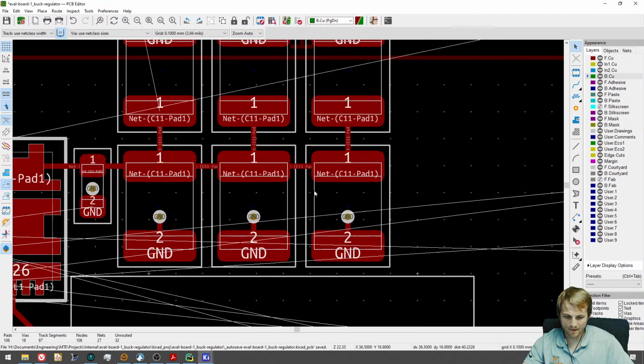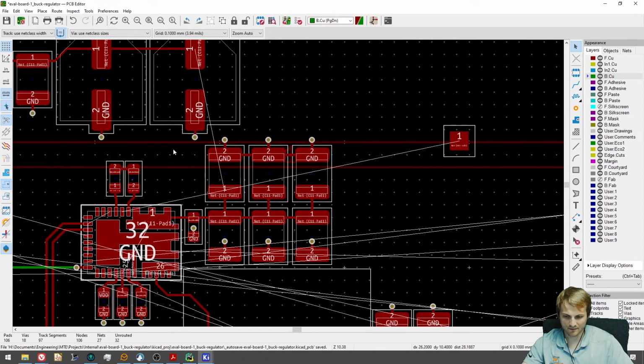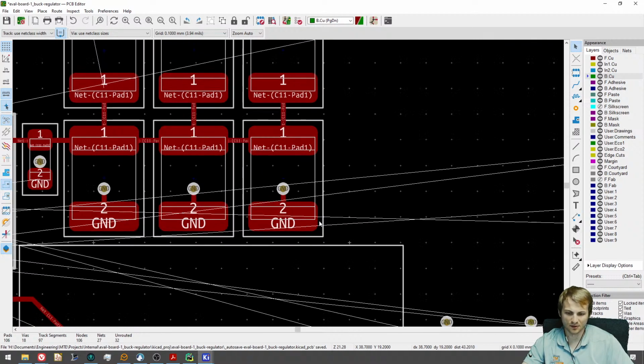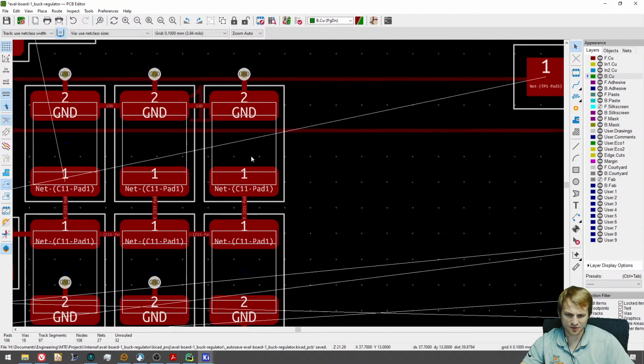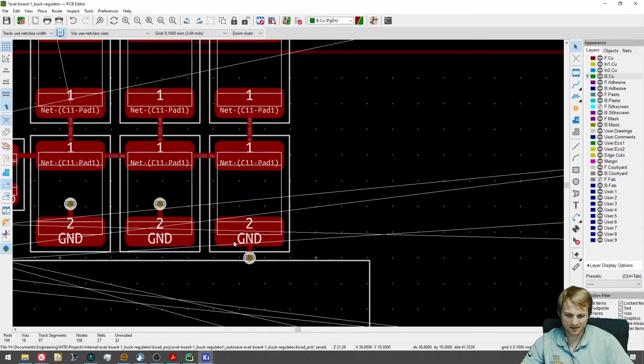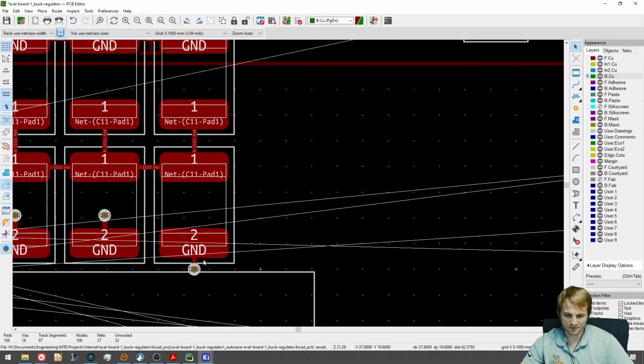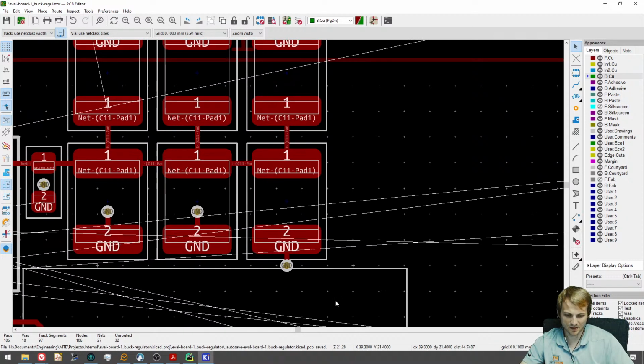Okay, so ideally, since we're going to have a pour here coming in, all this is going to be power. The goal with any ceramic capacitor is to lower the loop inductance. So if we had this, and when I said I shouldn't have done these, they should always be on the inside. So if this is its only connection to the ground pour, your loop from grabbing any power from the capacitor is going to be on this side, where if it's in here, you can grab it like this.